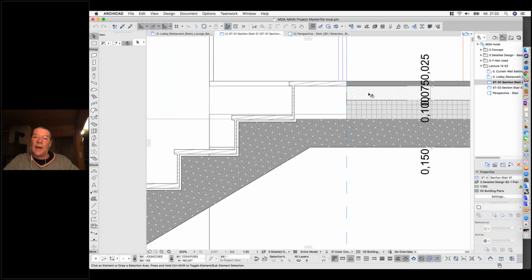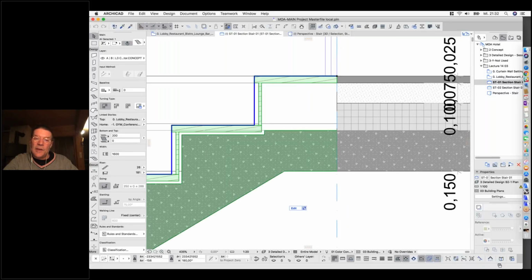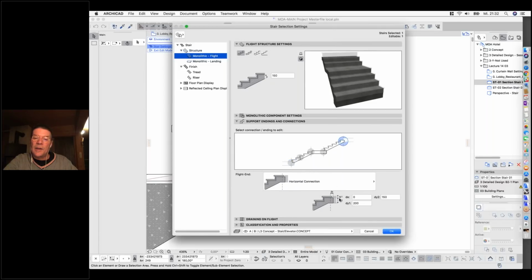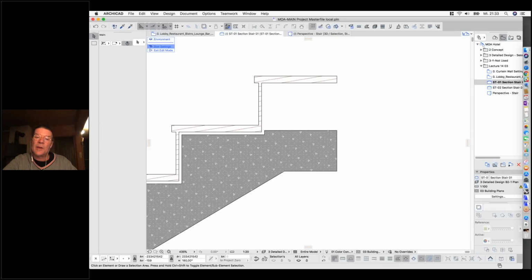Okay, nice. The setup here is again, if you look here, done in the stair settings. And up here, we have got three. One is DX. It is set up here on 0 because I didn't need it. And there is the DY1, and this one is again the setup above the load bearing slab, and the DX2 is the length here with the 150 mils. So this one is the DX2.